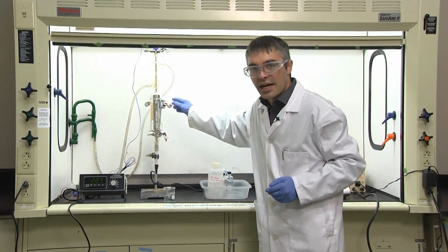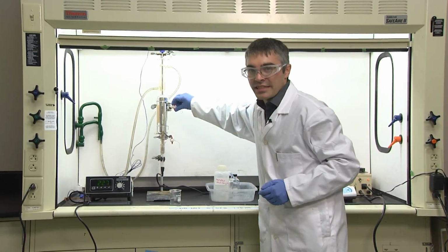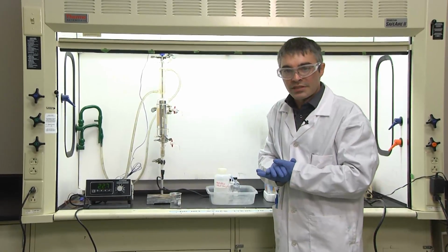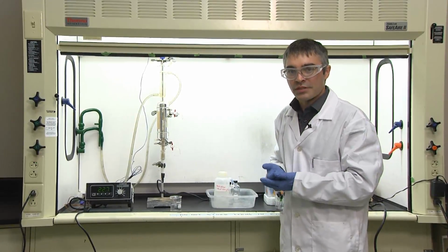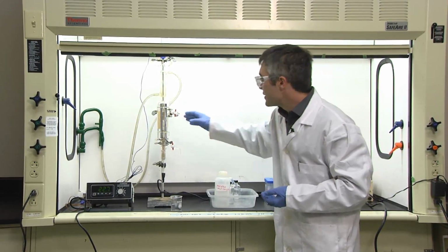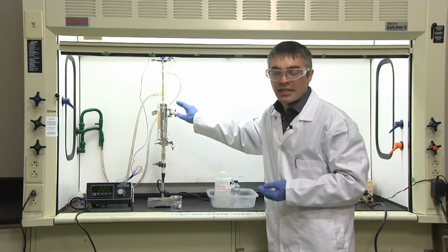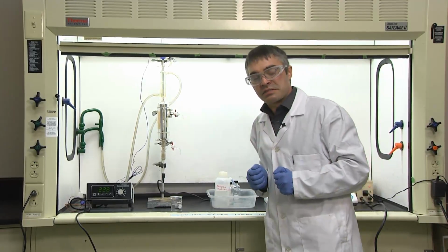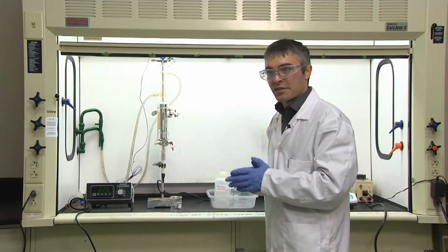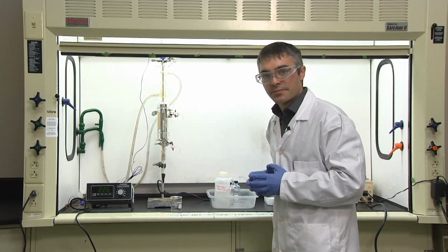Make sure you clear the lines before you take a sample, with the exception of the 2 samples that are required to take immediately and then subsequently. Make sure you read the instructions fully before taking a sample, as these will be very important data points for you to properly characterize both the mixtures and the azeotrope.